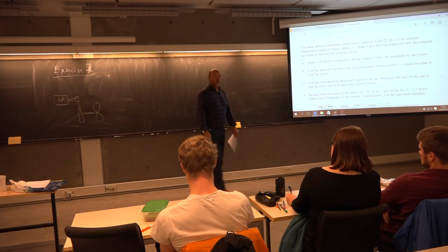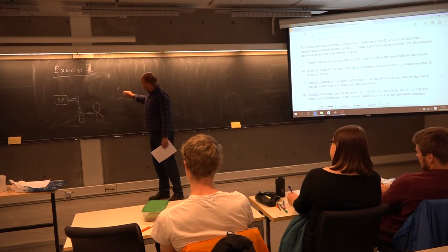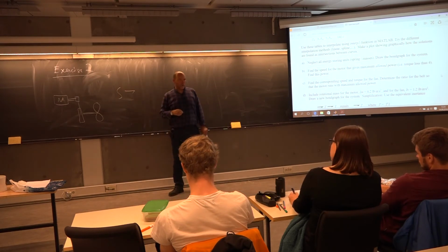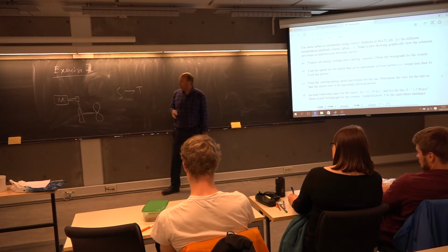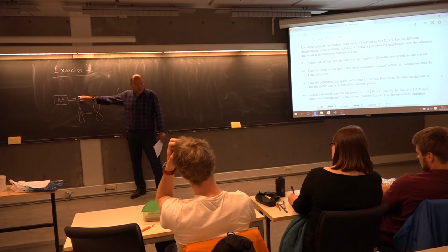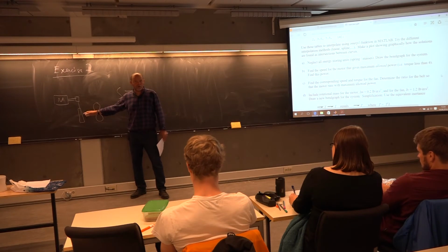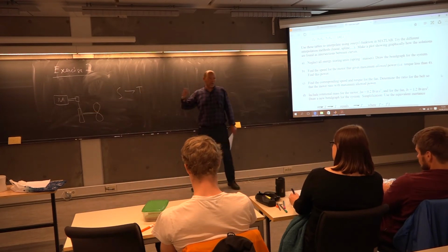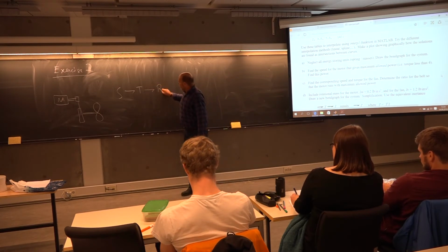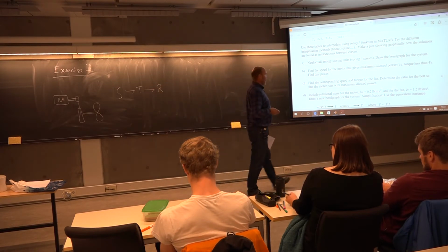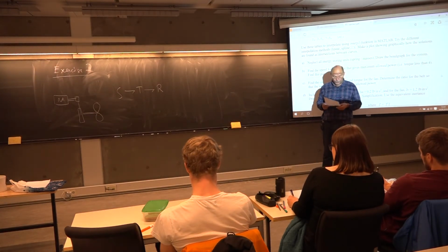The bond graph here you can draw fairly straightforward. It will be a source hitting, and it's no secret, it's going to be a transformer, because you have a direct coupling of rotational speed here. If you know the radius ratio, you will know the rotational speed on the other wheel. Hence, it is a transformer, not a gyrator. And on the other side, you will have the load, the resistance from the fan. So that will actually be the entire bond graph for the first part of the problem.